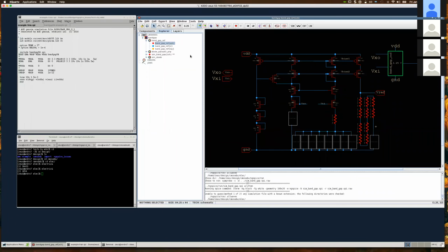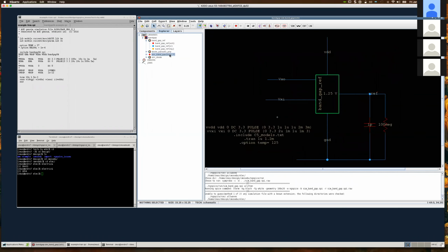This is a very crude circuit, and it's not actually even on this process, but it has similar performance and similar characteristics. Basically it has a startup circuit that will move the circuit fast to the point we want. But I wanted to show here that this is again a current mirror in a certain way. I broke the loop here, and I set it up in a way that I can sweep that point and see the impact of the